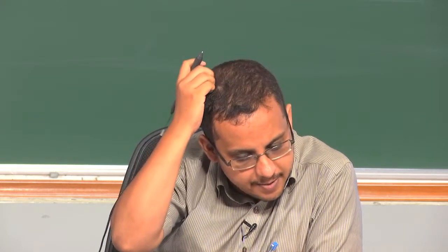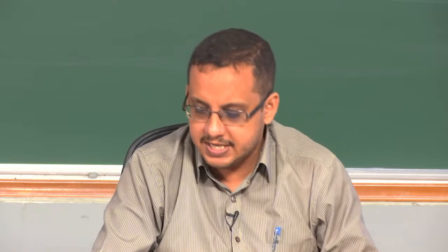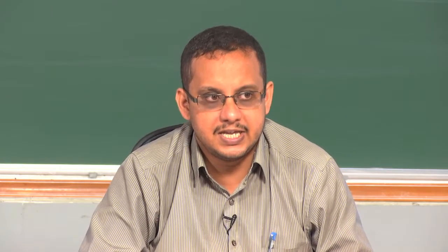So, therefore, our fundamental approach will change. We will not try to solve a PDE with a given boundary condition, but we will try to solve an inhomogeneous PDE, which includes the effects of the sources of sound. So, the effects of the sources of sound will be included in the inhomogeneity associated with the wave equation. Just like any non-homogeneous equation would imply that there is a right hand side to that equation, which is the non-homogeneous term. So, all the sources of sound would contribute to such right hand sides in the equation, and they will be called inhomogeneities, right.